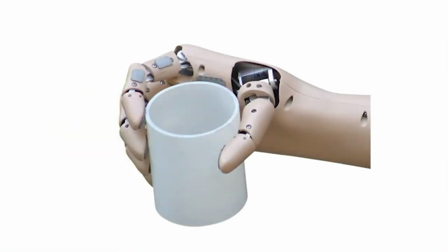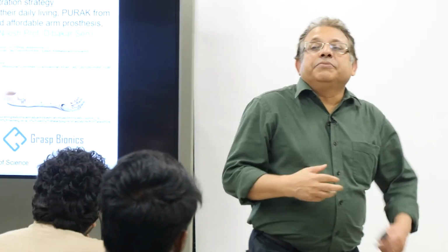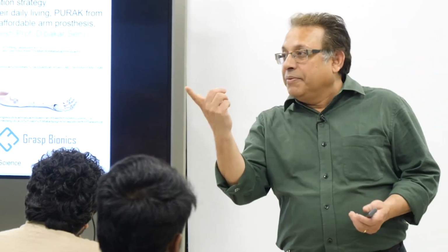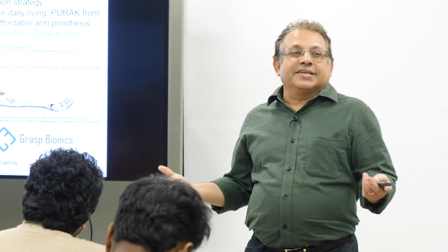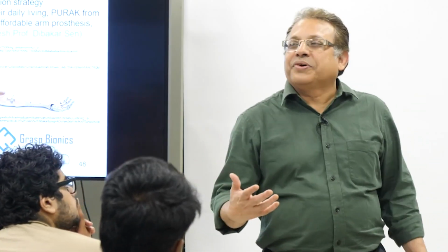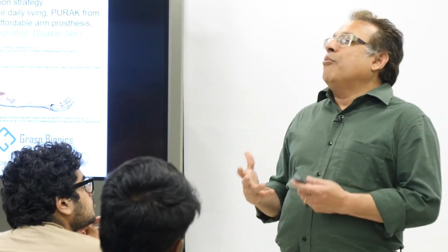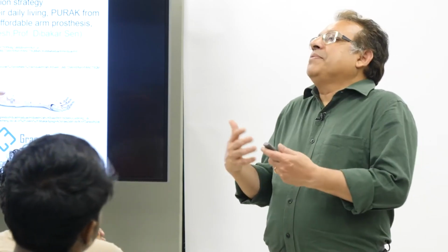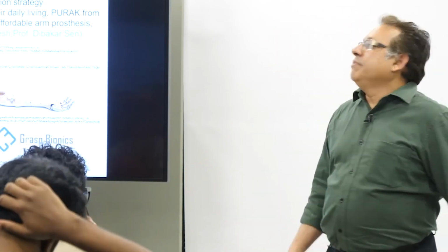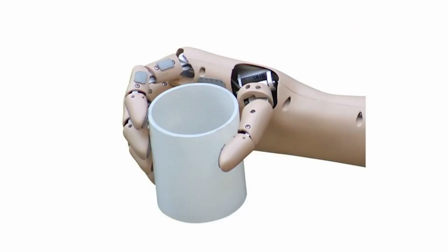And second challenge was in the prototyping, getting the right manufacturing processes. The same manufacturing process may be brilliant for making 200 parts, but terrible for making one. Remember, injection molding is a classic example, right? So actually one problem that you should look at, or some of you should look at, is how do I create a mold that can be changed into another mold, and that can be changed into yet another mold. Molding is a major challenge where the cost is involved.